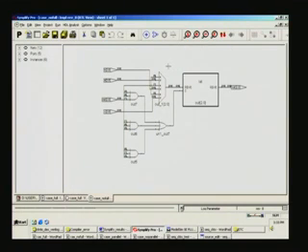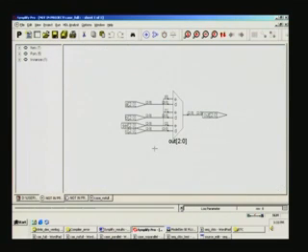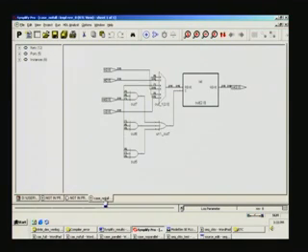What we had earlier was actually this one, and now this is for Synopsys full case, whereas for no full case you see that in addition to this, extra gates have appeared here. So, 3 plus 4 gates plus one latch is also there, and a latch is detrimental for making a really working hardware. We have pointed out earlier during the RTL guidelines.